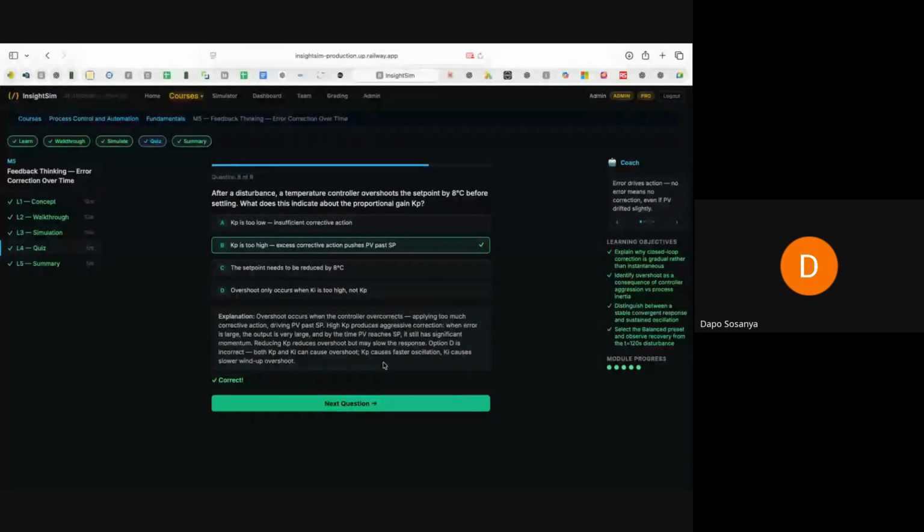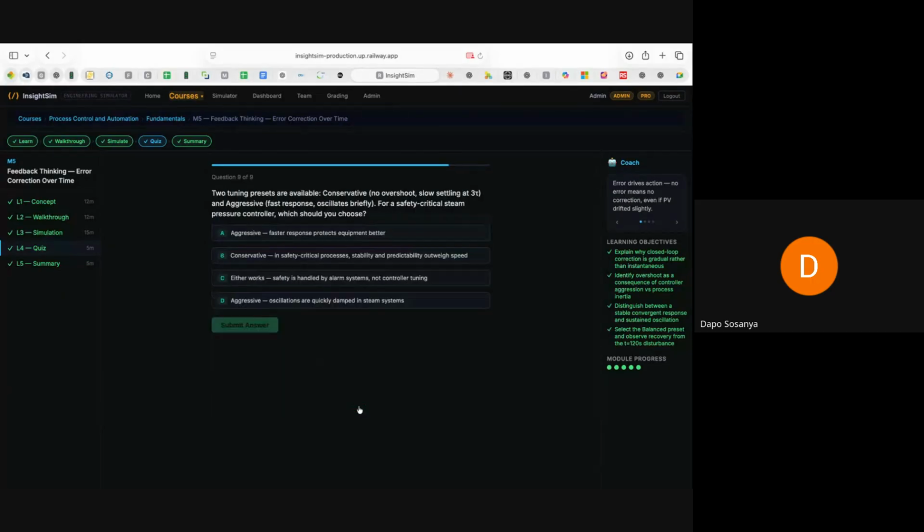There is pressure increase year on year, and so on. So you tune it, you adjust your KP, KI, and your KD. Then they measure for another 2-3 months, and they discover that there is a reduction in energy consumption. That translates that the control engineer has given money to the plant and has increased the plant bottom line.